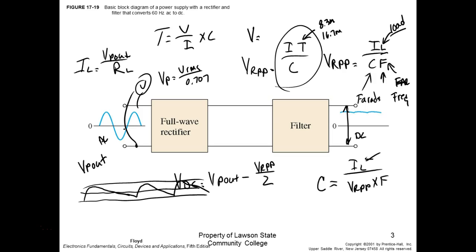As soon as you short two windings, then usually it cascades after that, but it'll cause your turns ratio to change. So you'll get a lower turns ratio on the output. So this is where you would actually measure the output of your transformer to make sure it's giving you at least the voltage that you want, right? You understand that. And what's the next thing that could be the problem?